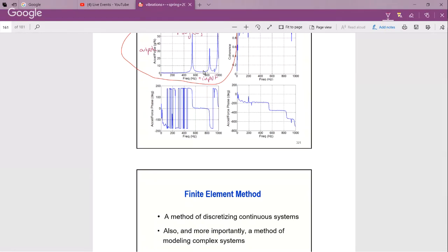I've got my structure sitting on fancy suspension. It's a low frequency oscillation of the low natural frequency of whatever the structure is sitting on, this elastic foam. There's a lot of damping, but if it moves around or bounces around a little bit, then it's not going to be real clean. That's why the coherence is bad too. But that's all that is. We ignore it. You can see there might be a little bit of something down here. It might show up even more with stuff we do today because the one piece is a little heavy. But these three here are real clean. Plus 90, minus 90. All right. Any questions on this one?